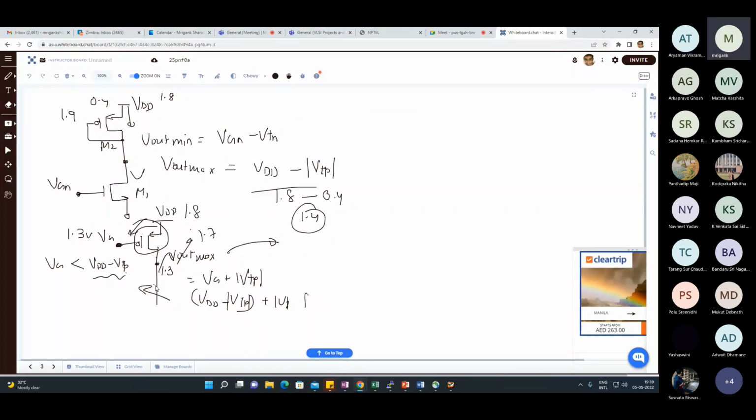Here the DC bias point at the output is not stable. So single-ended common source with this kind of load, you can't use it practically. You just simply use this kind of configuration. It is not possible because you need to bias it. Is that clear?